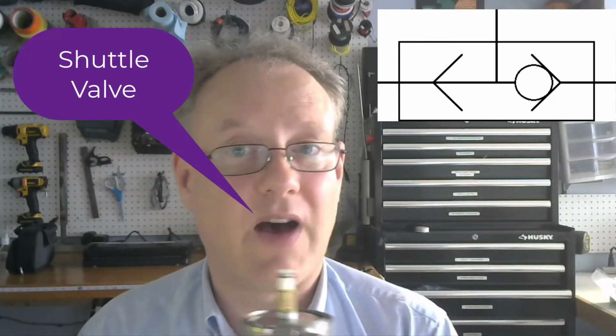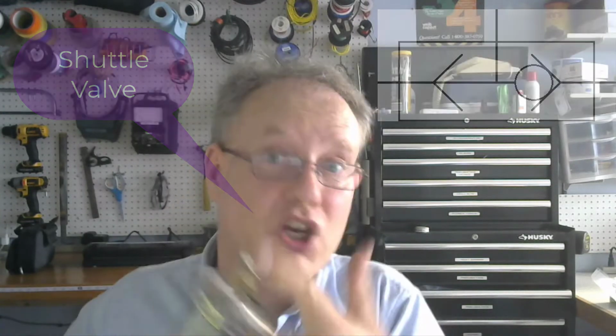We can use a shuttle valve and an accumulator, or even just a tank. An accumulator is just a small air tank. So I can put some pressurized air in here, just like a backup battery or a backup system, where if the main system pressure is, say, set to 80 psi and it goes low, and I've pressurized the air in here to 70 psi, then if that main pressure is gone for some reason, this guy takes over and he wins in the check valve. And now this 70 psi is actually going downstream into the system, and it's running whatever actuators.